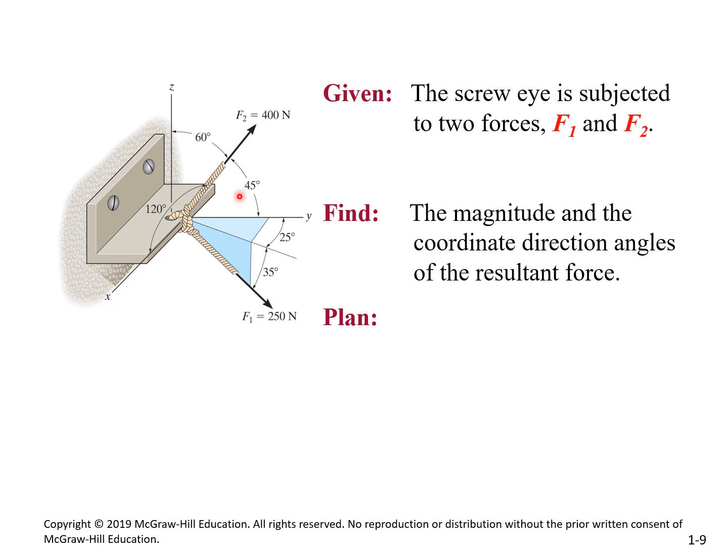That's what we did in statics. How would I do the analysis of F1? You want, so this is 35 with the z-axis. What I will do, I will create an imaginary z-axis here, and I will say that this is F1. What do you think? Is it cosine or sine 35? Cosine is always with the axis that has the angle. The sine is the one without the angle. So that's going to be sine 35, correct?